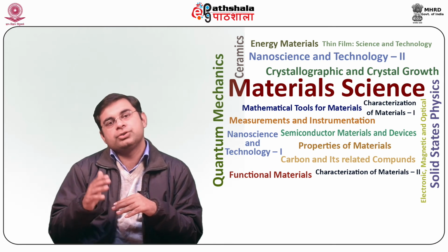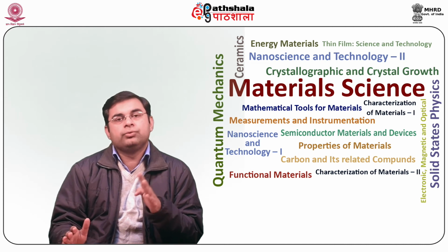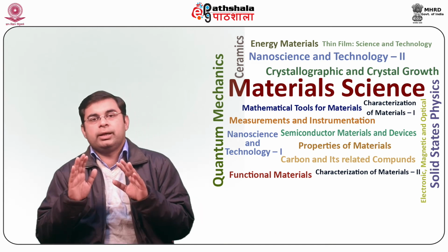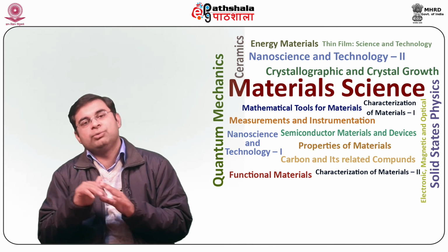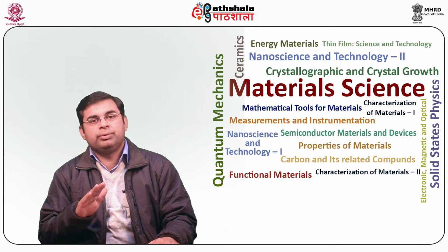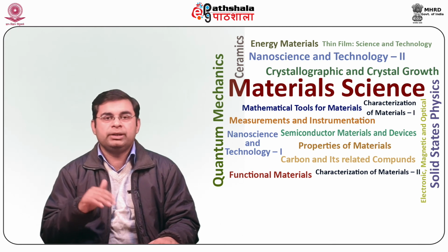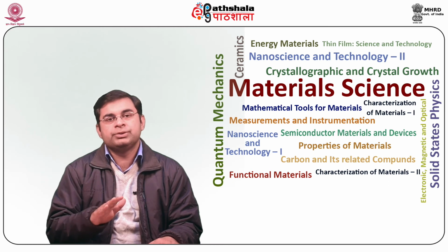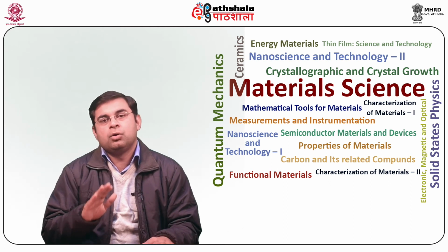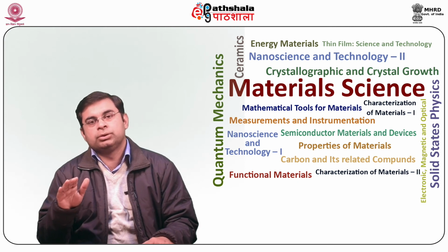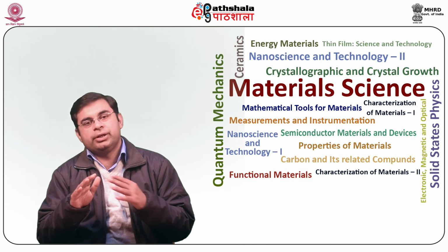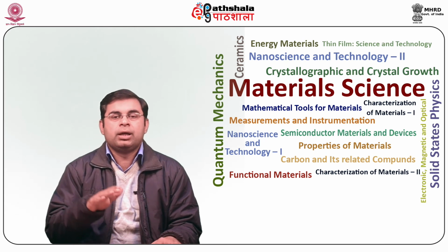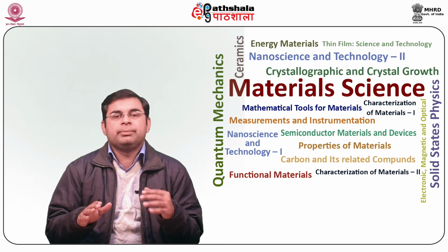Dopants can further cause a shift in energy bands with respect to the Fermi level. The energy band of a dopant having the highest concentration lies closest to the Fermi level. As the Fermi level is constant for a system in thermal equilibrium, stacking multiple layers of materials having varying properties results in novel properties caused by band bending. The most common example is the p-n junction, which has unique properties generated by band bending, which is a consequence of joining the bands in the contact region of P and N-type materials.